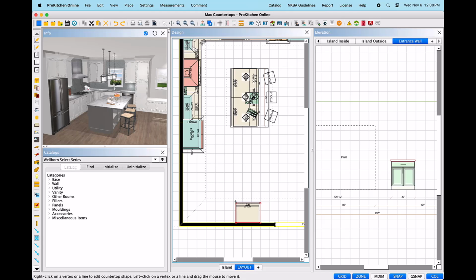To change the dimension of the countertop, left-click once on the red line of the side you wish to move. It will appear as if the countertop has disappeared momentarily until you move your mouse. The outline of the countertop will become black in color once again, and you will be able to move the selected line in or out of the existing shape. Once you have extended or recessed the countertop to the desired depth or width, left-click to secure. The mouse will remain a crosshair, so you may continue editing this portion of countertop.